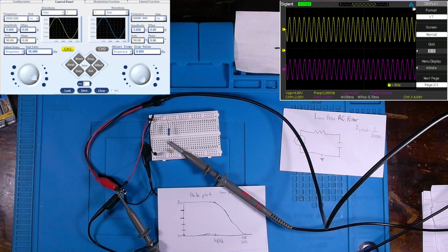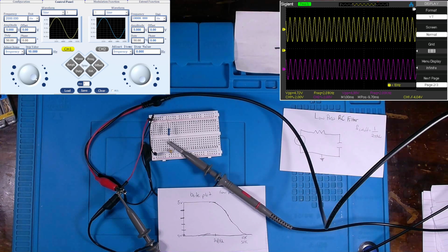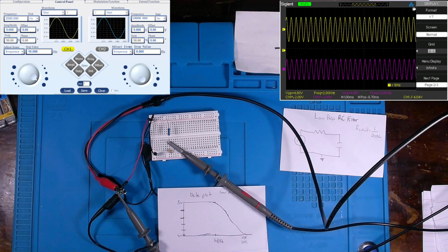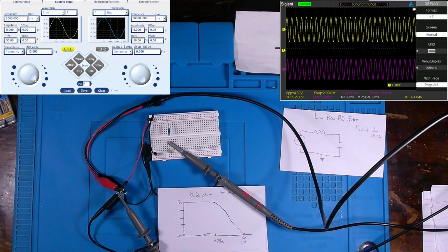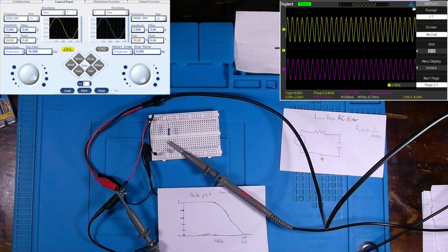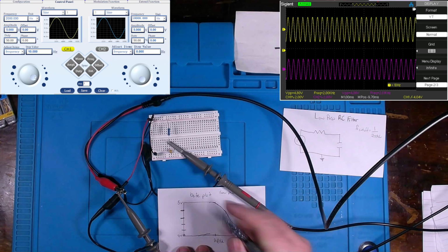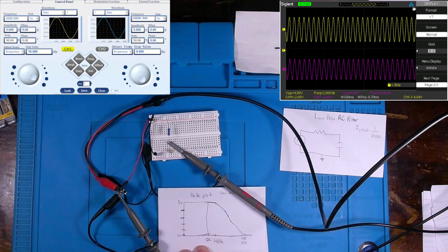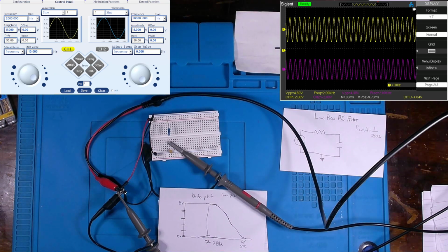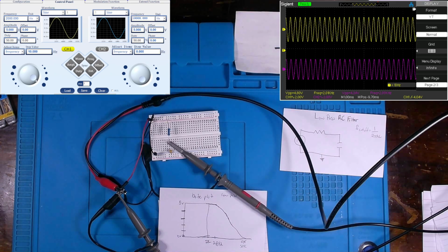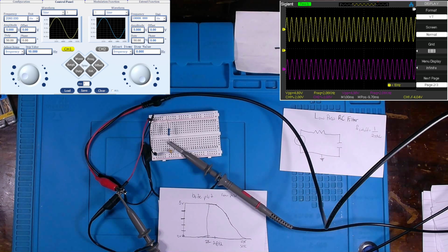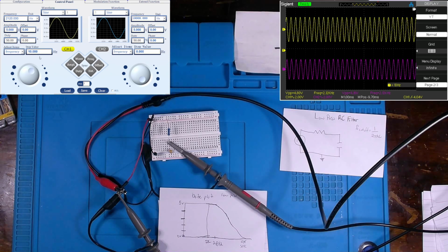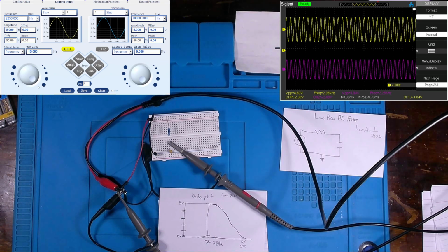Let's see, 4.8 volts on our input frequency, and approximately 4 volts on the outside of this filter, on the back side of this. Okay, so we're starting to actually see this drop occur right around 2K. But we've still got our frequency there, so that frequency is still going to be reproduced at the speaker. But as we start going over that, look at that. We can see the amplitude on channel 2 starts to diminish significantly.